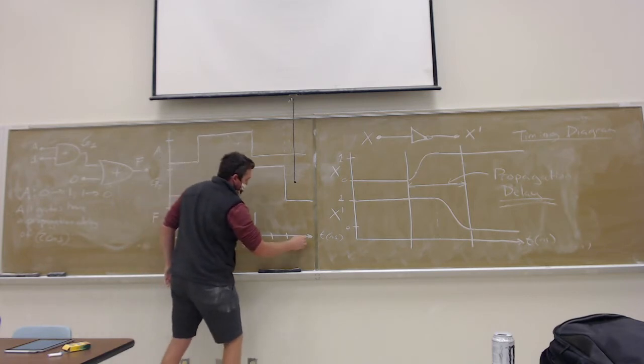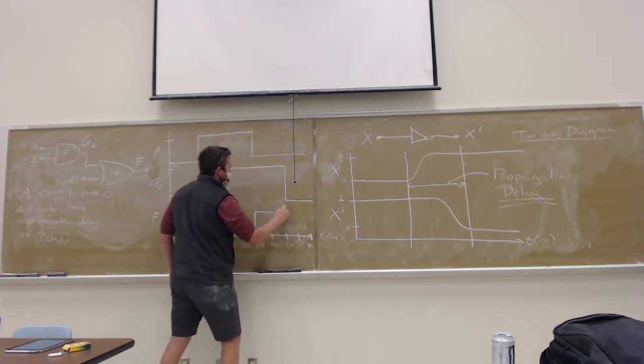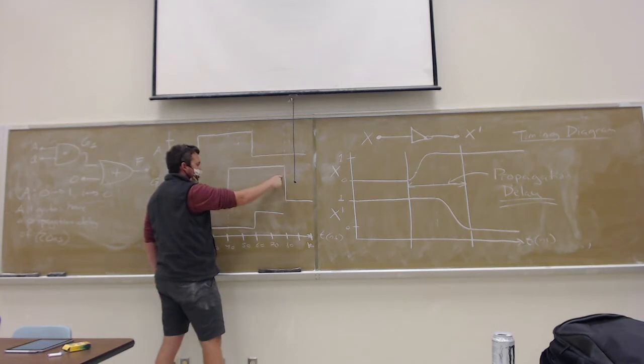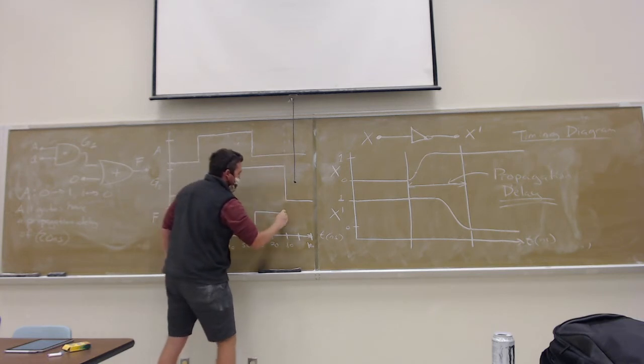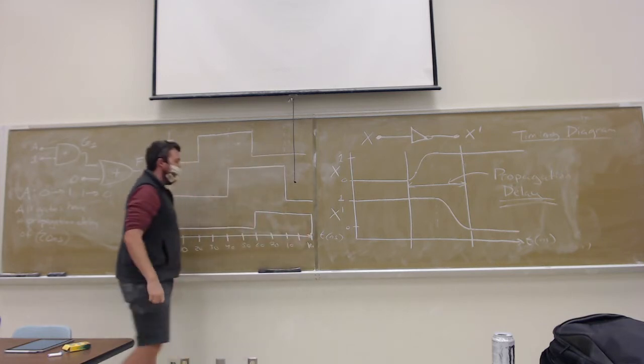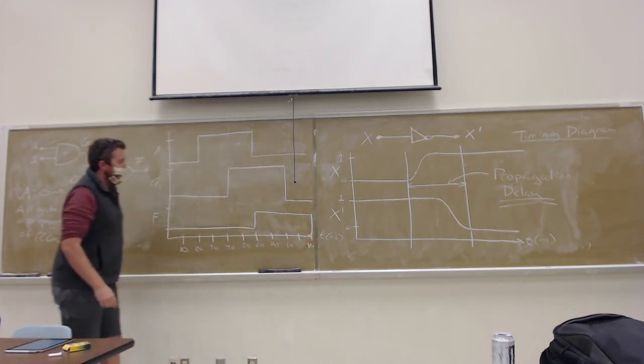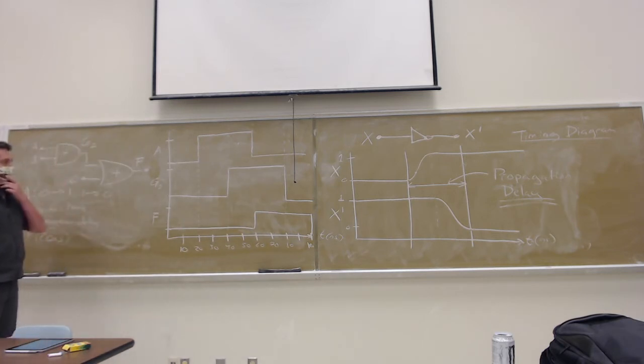And it stays at 1, actually 80, 90, if we call that 100 out there, until G1 comes back to 0, and then it's 0 or 0, but there's still 20 nanoseconds of delay before it comes back to 0. So there at the very end, it will drop back down to 0.